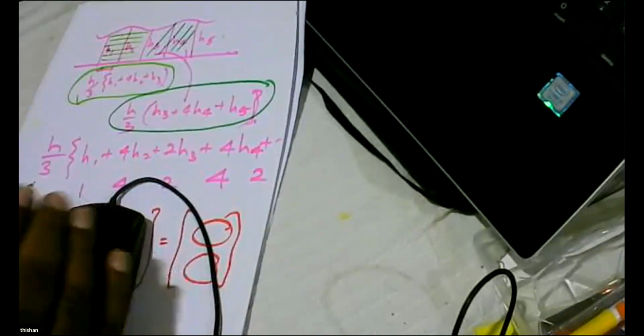The rule is, the pre-stressing force you select based on the Magnel diagram may not be sufficient in a continuous structure. You have to look at it additionally, and that is to make sure a concordant profile exists at each support.